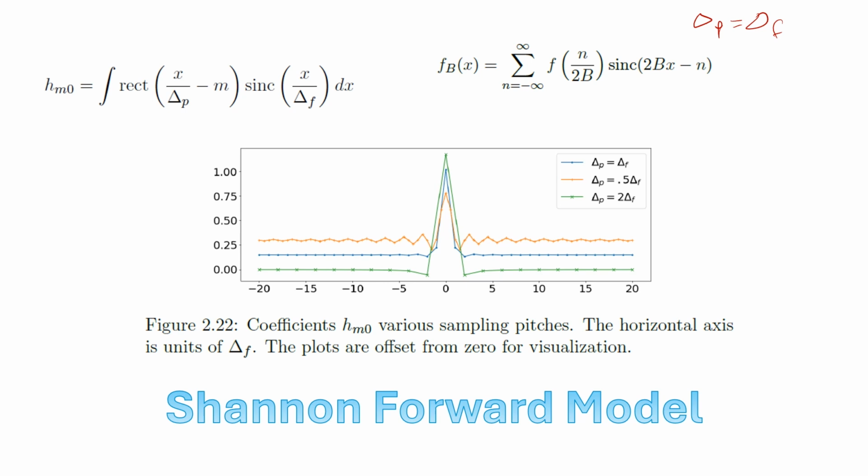The middle curve is sampling at Nyquist, where you start to see some of the sinc, and then of course the upper curve is the oversampled system where the sinc oscillation is apparent. These curves are offset from 0 just to allow you to see them, and of course these are discrete values at each point where we've drawn the curve, with the line in between just for visualization.